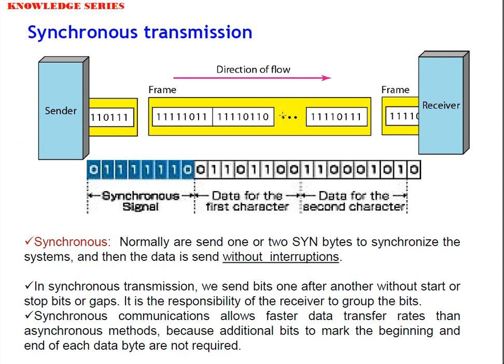So we will have a flag as F, then I as idle data, then D as the data which we need to process. After that, if the next information starts, then again we will put F as a flag, then I as idle if it exists. Otherwise the data will be there. So the flag will always be there to identify the start of block boundaries.